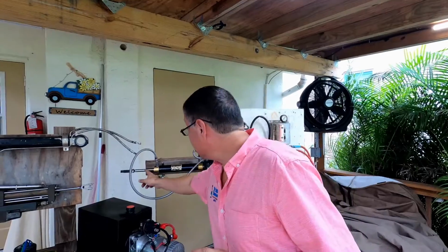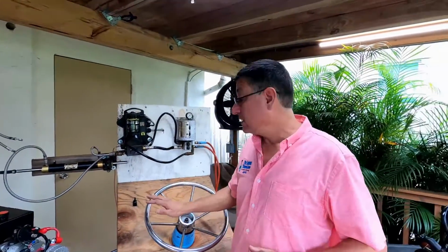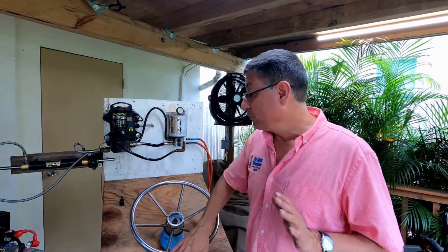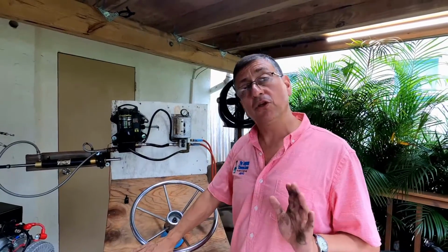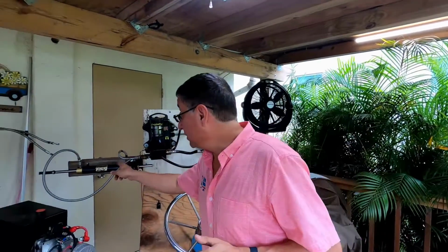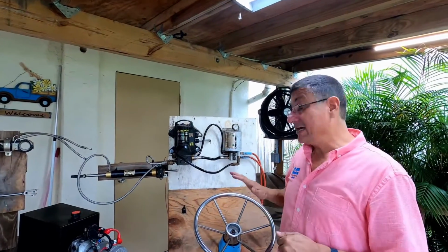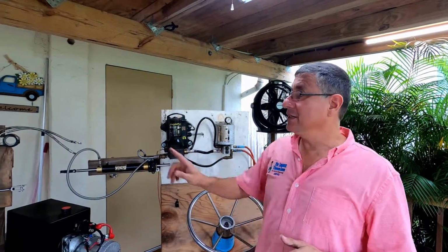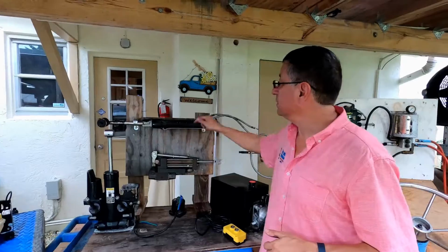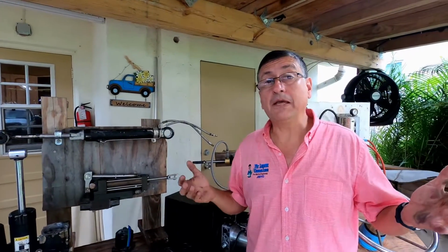For that reason, this type of cylinder is commonly used for power steering, because we need the force applied on both sides to be equal. If not, when you move your wheel in one direction, it's soft, but if you move the wheel in the other direction, it's hard. For that reason, this type of cylinder, double port, double shaft, is recommended for steering applications. And this type of cylinder, double port, single shaft, is used for different applications.